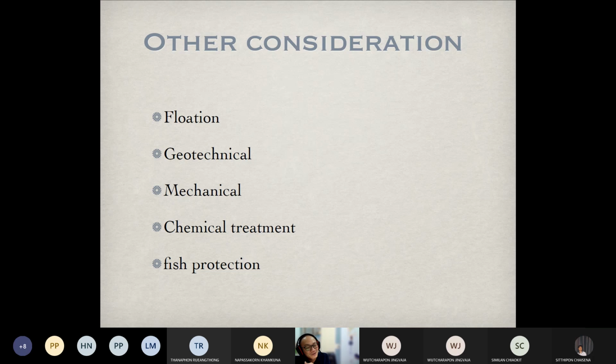The fish also sometimes they have found in the sedimentation basin. So in order to avoid it, we should have a kind of screen to prevent the aquatic organisms from entering our plant, and sometimes they may get stuck in the pumping facilities.